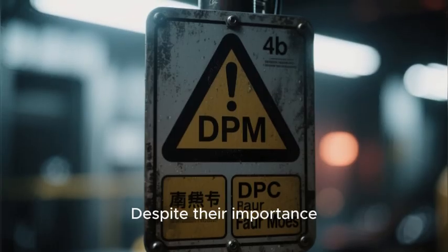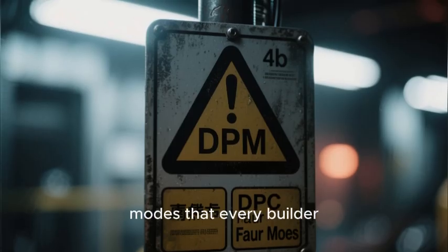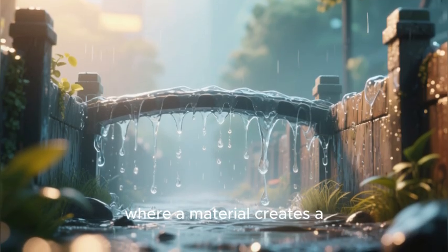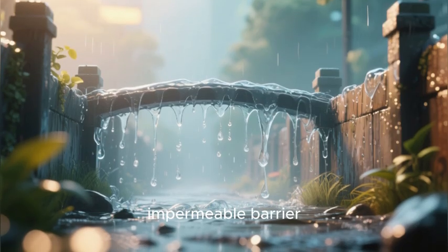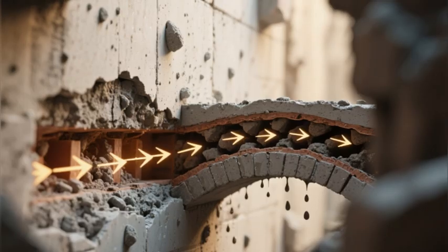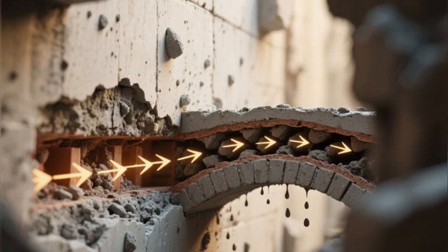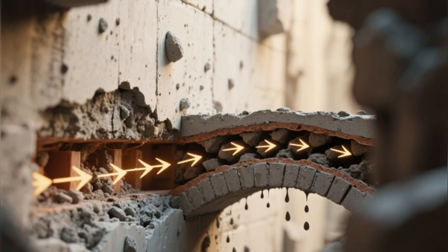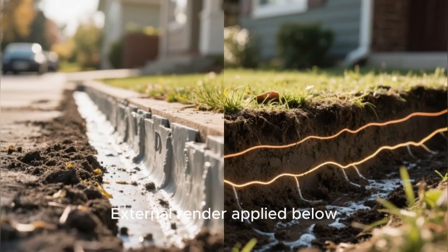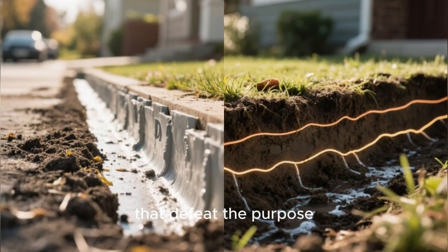Despite their importance, both DPM and DPC systems are vulnerable to specific failure modes that every builder should recognize. The most common issue is bridging, where a material creates a pathway for moisture to bypass the impermeable barrier. For DPCs, the most frequent bridging occurs when mortar droppings accumulate in cavity walls during construction, creating continuous material connections between the outer and inner leaves that effectively short-circuit the DPC. External render applied below DPC level or soil and paving build-up above it similarly create bridges that defeat the purpose of the barrier.